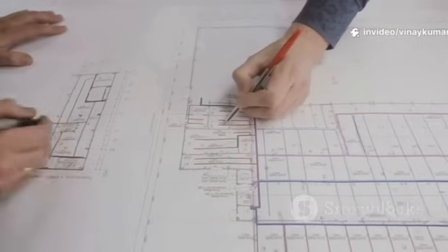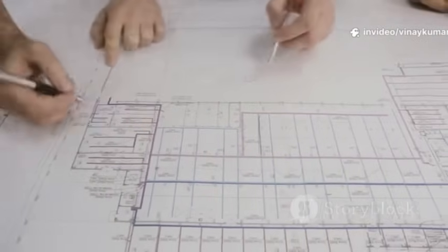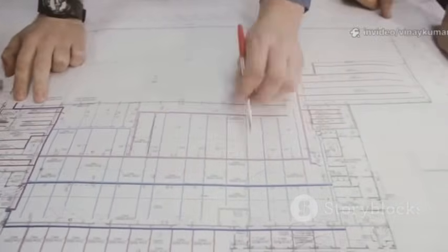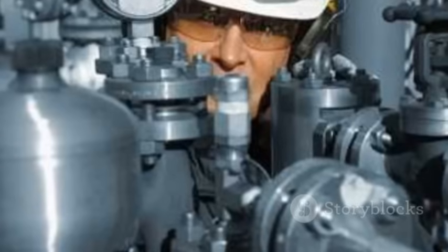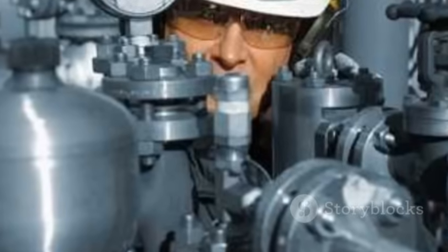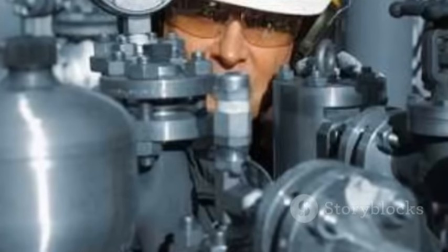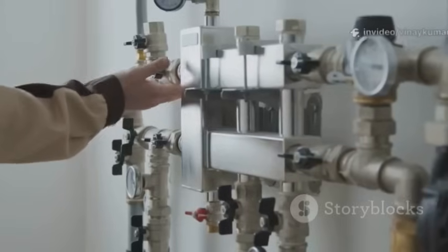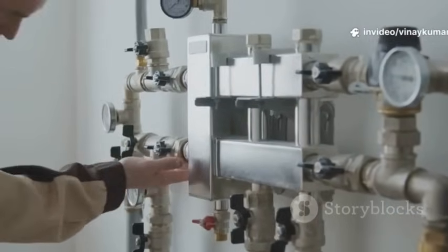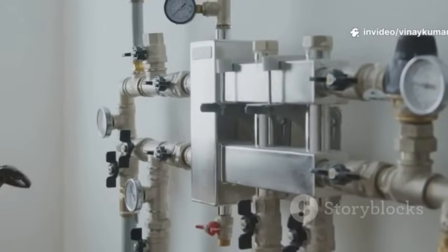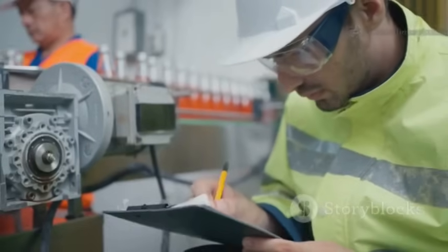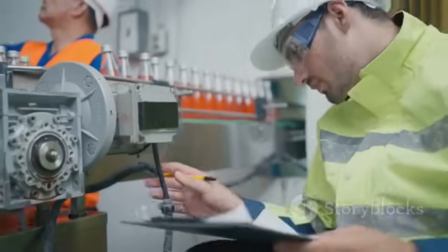The purpose is to ensure that the as-built facility matches the as-designed safety specifications. Sometimes things look good on paper, on the P&IDs and in the procedures, but the reality on the ground is different. Maybe a valve was installed backward, or a crucial piece of instrumentation was never connected. The PSSR is the hands-on check to find those discrepancies.